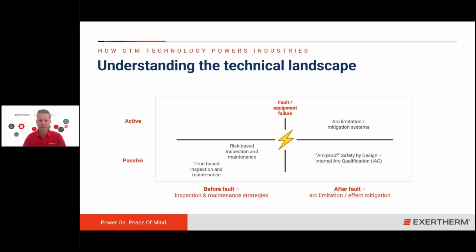It's about identifying an internal arc occurring in the equipment, for example, using light and high current information, leading to an immediate circuit breaker tripping, or in a next stage, triggering a device that takes the three-phase voltage to earth connection to the ground for reducing the incident energy from expanding the volumes and burning the metals and epoxy in the first place. Not only keeping people relatively safer, but also limiting the damage to the equipment, and in consequence, the degree of servicing and maintenance or replacement works that would need to happen.